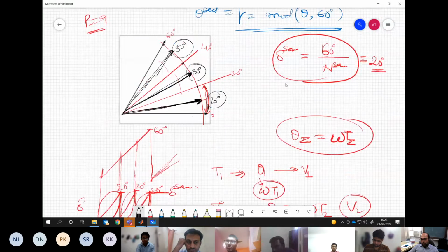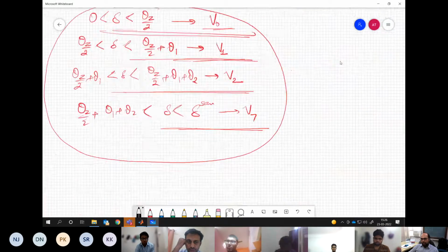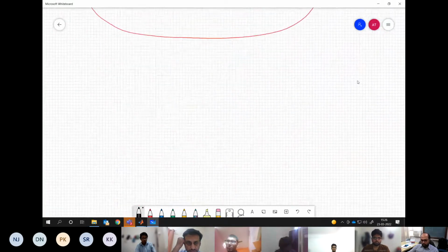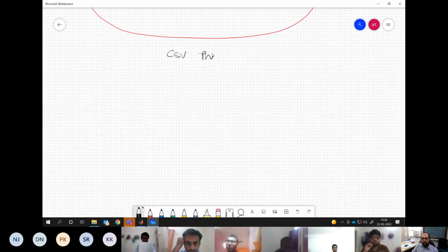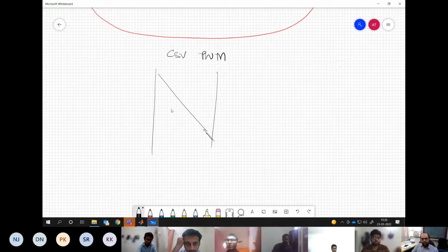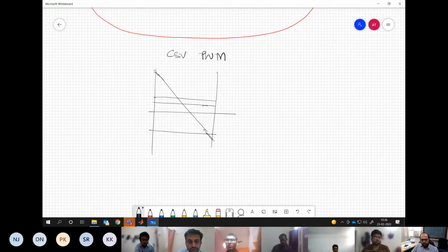Now we move to the next question. How do we apply the vectors? One option for conventional space vector PWM is that we can apply them similar to sine triangle PWM. What do we have in sine triangle PWM? We have the carrier falling like this, and three modulating signals. Ultimately, we have either the plus plus plus vector applied first, then plus plus minus, plus minus minus, or minus minus minus.